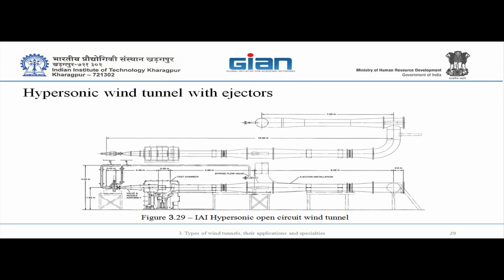For Mach 12, we need around 1400 K. That's theoretical, 1400 K at 100 bar. Your tunnel is only 750 K total temperature. So if you are running with a smaller pressure, then what is the P naught, the stagnation pressure? 30 bar. Technical note 11135?